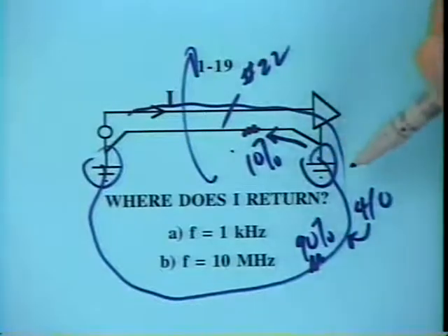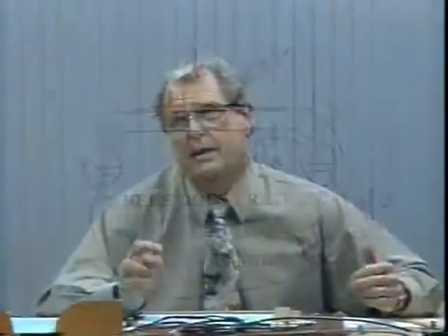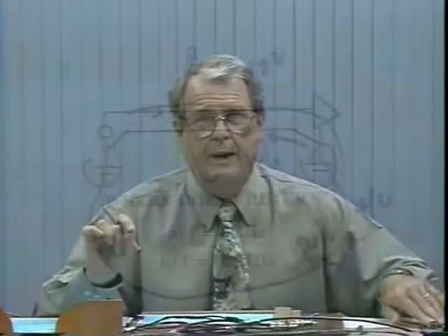What do we do for low-frequency currents? We don't give them alternative paths. Low-frequency currents, the best way to think about them is they will take every path available. Not exactly to the same degree, but they will take every path available. So make sure that if you want a low-frequency current, that's anything below a few kilohertz, you want that current to take a specific path, the best idea is to only give it that path. No other path possible.